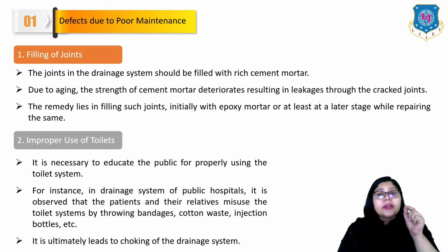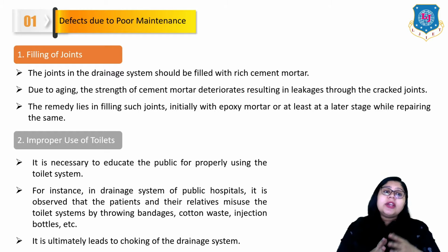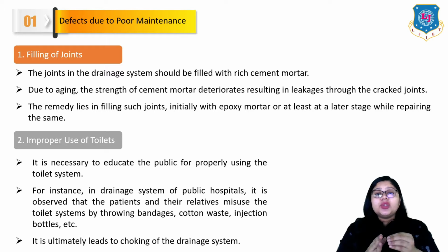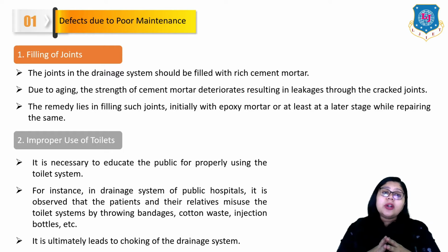The joints in the drainage system should be filled with rich cement mortar. Due to aging, the strength of cement mortar deteriorates, resulting in leakage through the cracked joints. The remedy lies in filling such joints initially with epoxy mortar or at least at the later stage while repairing the same.